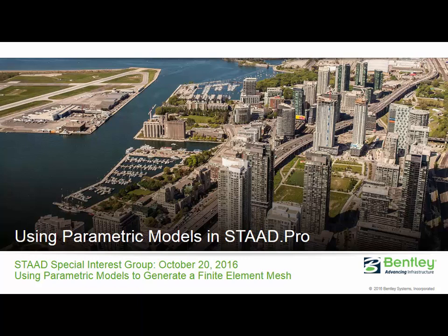Now this method does offer some advantages over some of the other methods that you'd see in STAAD Pro. First, it enables you to preview the final mesh state of the wall, slab, or panel before deploying the mesh entirely into the remainder of the model. Several trials or prototypes can be visually examined before committing the most suitable one to the input file. This greatly minimizes the inconvenience of ending up with an undesirable meshed panel.